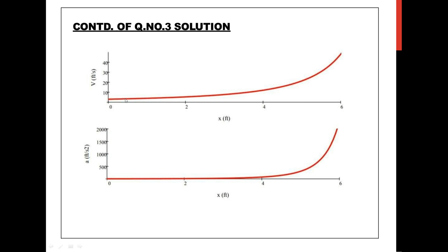We can see the velocity will increase with displacement as the area is decreasing, due to the continuity equation. And also in acceleration, you can see it's mostly equal, and at the end point, that is at the exit, acceleration vastly increases.